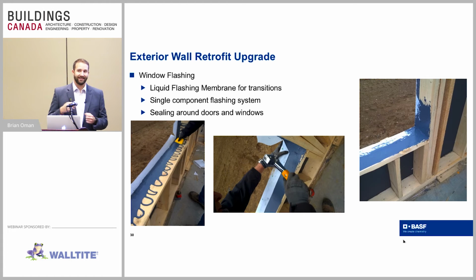So depending upon the level of the energy retrofit you're going to do, we may want to take a look at the window flashing, as I said. In the case study that we're showcasing here, the windows are actually newer. So the homeowner decided not to replace the windows. So the flashing details were done such that it was flashed directly into the window frame itself, into the flanges of the window.